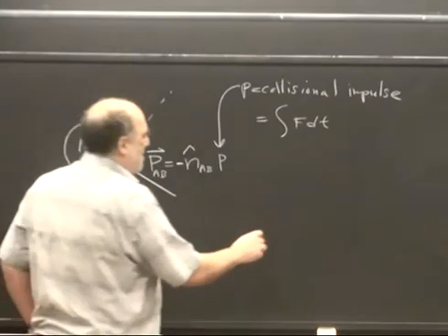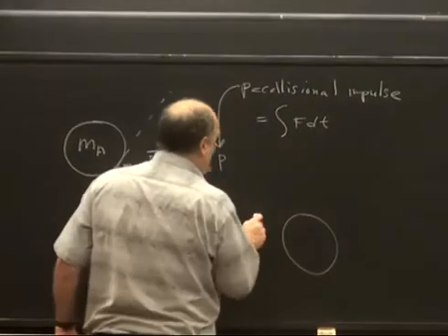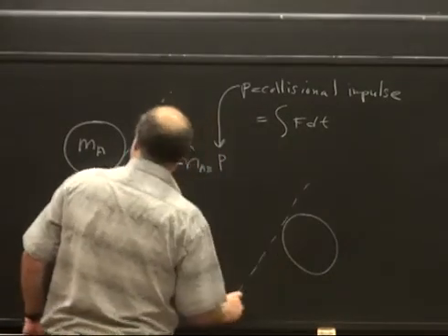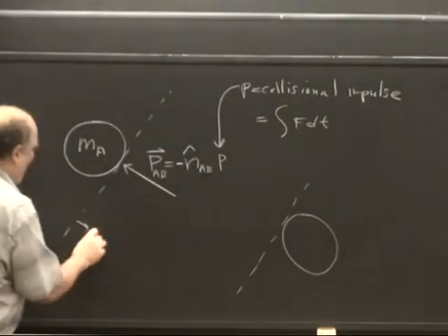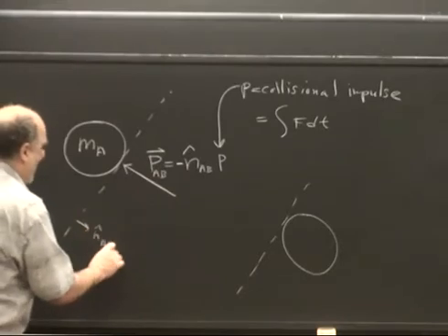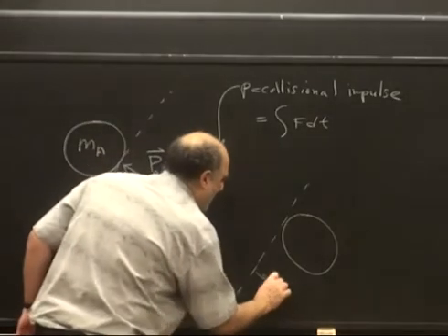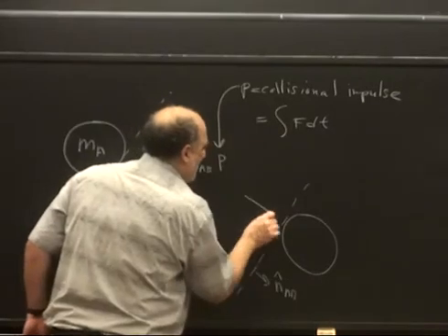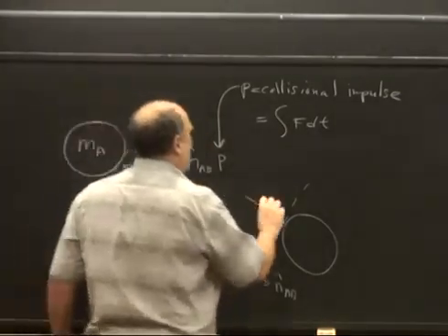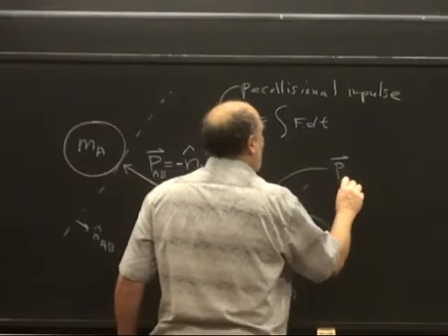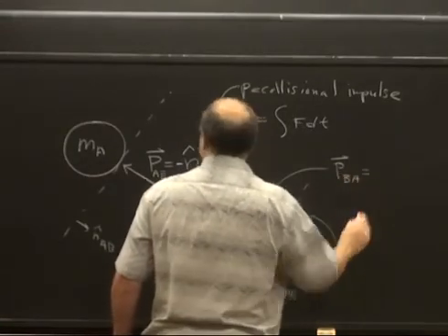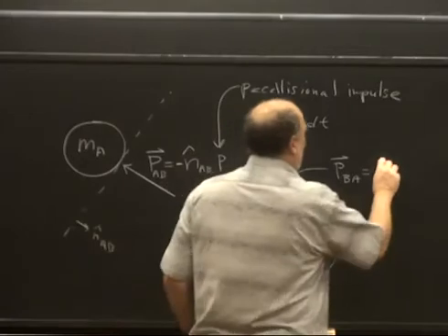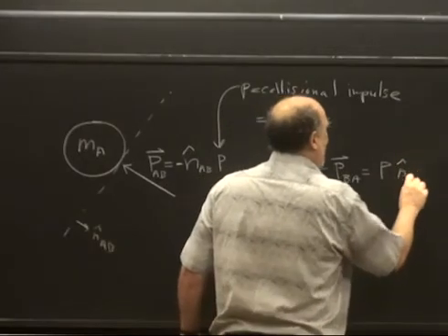Now we have similarly the free body diagram of B. We've got the same normal plane here. Here we have NAB on the side. Here we have NAB on the side. And then we have a collisional impulse here. And this is the impulse on B from A. And what is that equal to? It's minus this one, so it's P times NAB.